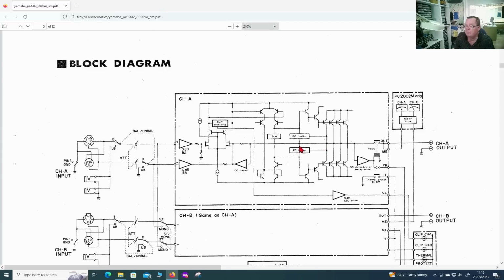This point also feeds back into the differential amplifier. This is the feedback circuit. So you have the signal coming in. This is a constant current source, this little symbol here. We have a proportion of the output signal coming back, and it's effectively between the values of the resistor here and the resistors here. This sets the gain of the amplifier.